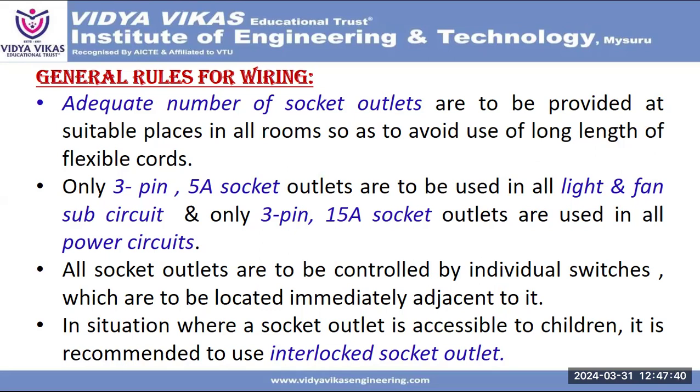Mosquito avoider, so many things are there. Okay, only 3-pin 5 ampere socket outlets are to be used in all light and fan sub-circuits, and only 3-pin 15 ampere outlets are to be used in all power circuits.